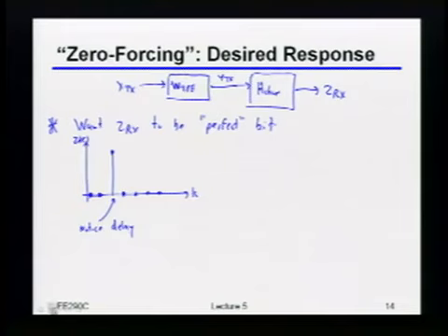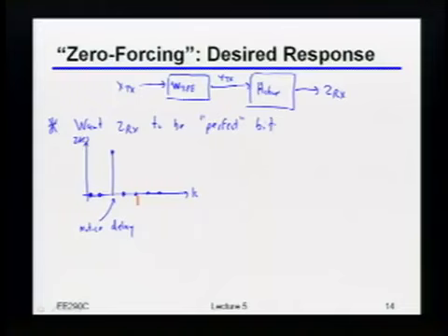Okay, so what you have to be careful with there has to deal with 2 things. It has to deal with, A, the delay of the channel itself, and B, the delay that you're quote-unquote inserting in your equalizer because you have precursors. Just be careful with that because it's a source of great confusion. If you don't place the desired thing in the right spot, your equalizer won't be doing exactly what you thought it was. Okay? So you have to insert the zeros in the right spot to get it to behave the right way. Okay?